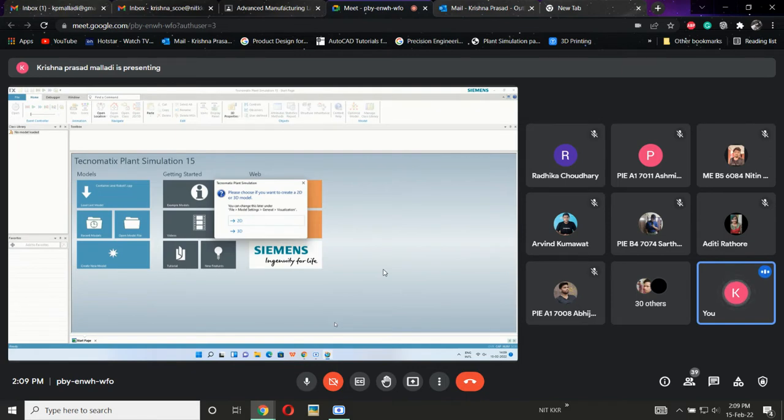In both cases, we'll try to reduce the bottleneck, by using the same conveyor as well as by using the buffer. If place is a constraint and I am getting the blockage, then definitely I'll go for buffers. In a buffer I can increase the capacity so that the production won't stop at any point of time. If place is not a matter, then I can increase the length of the conveyor.